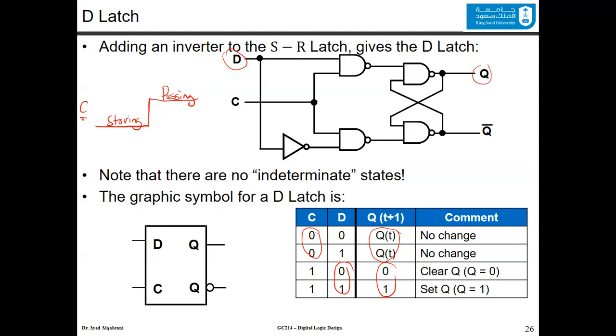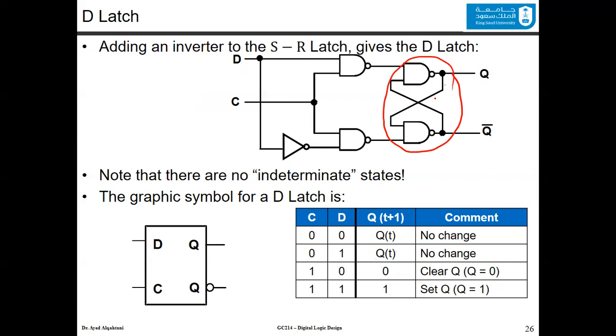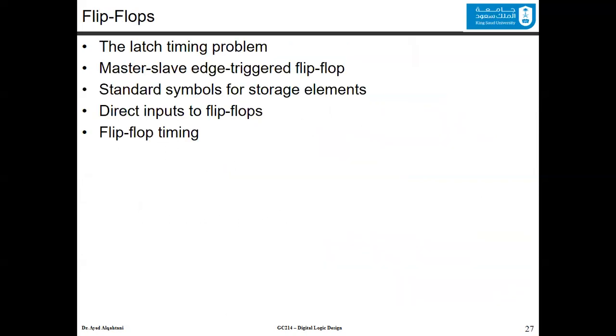And that's one of the critical circuits, as we said. The reason we call it a sequential circuit component is because you can store a value here. You can store a value here. Basically, whenever you have a feedback in the circuit, it must be a sequential circuit. Now, after we introduce this important circuit, we will move to the flip-flops.